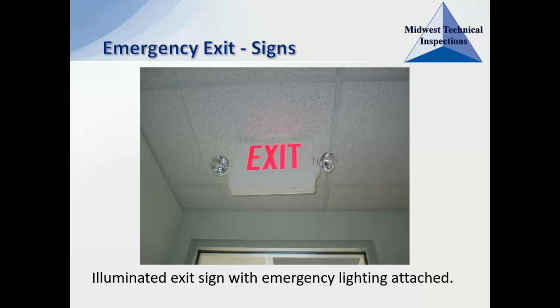But they need to be visible in low visibility, so that's why we need them to be illuminated. They need to be above the door, not on the door, that way if you open the door, you can still see the exit sign.